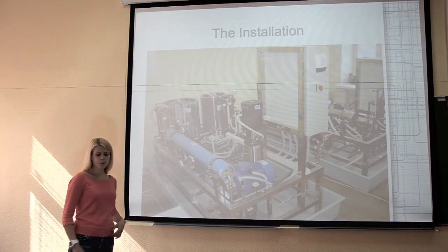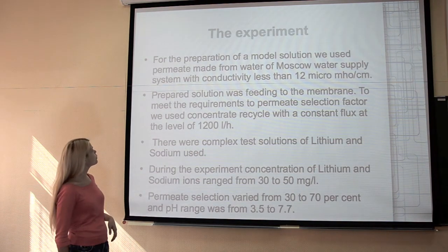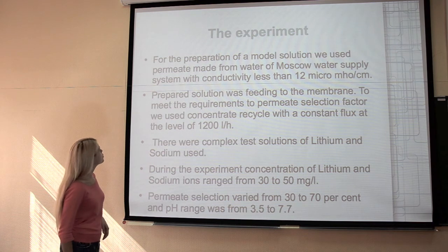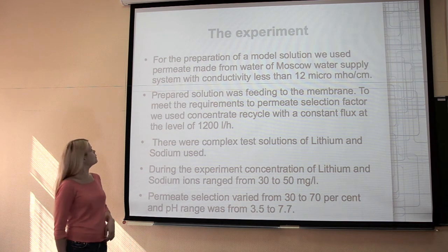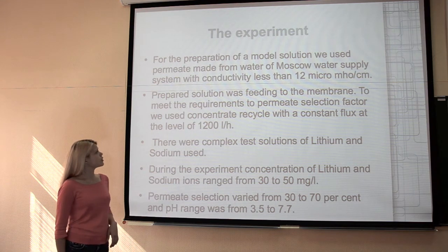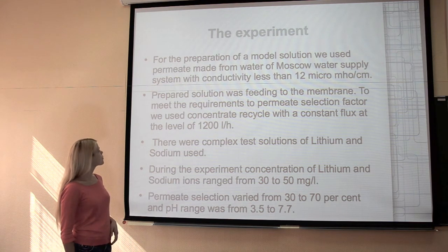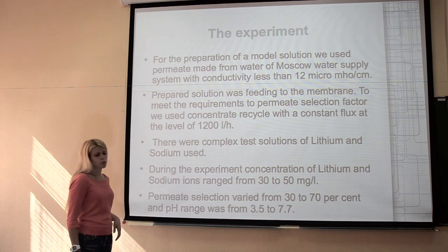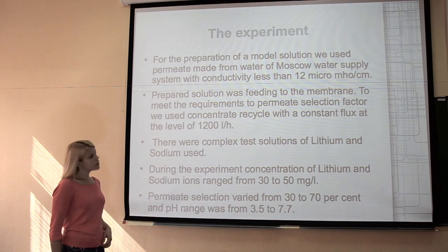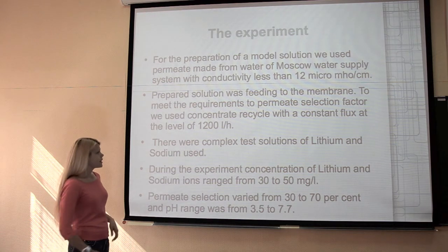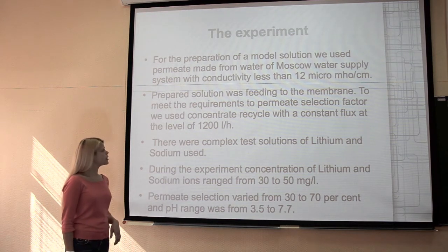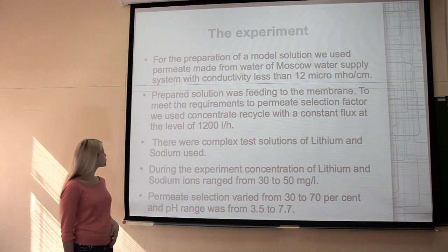About the experiment. For the preparation of a model solution, we used permeate made from water of the Moscow water supply system with conductivity less than 12 microsiemens. The prepared solution was fed to the membrane. To meet the requirements of permeate selection factor, we used concentrate recycle.